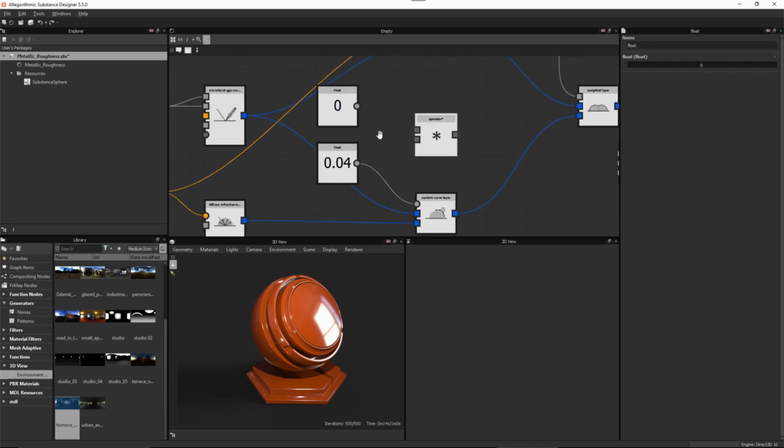Okay, so what we do in the actual physically based shader is that when you look at the range of the dielectric F0 value, okay, so like I said, we have 4%, which is the default. It's going to range in the shader from 0, which represents air, all the way up to 0.08 or 8%, which is like going to represent things like gemstones and such. And that's the range that the shader remaps to when it comes to this specular level. So we got 0 all the way up to 8% or 0.08.